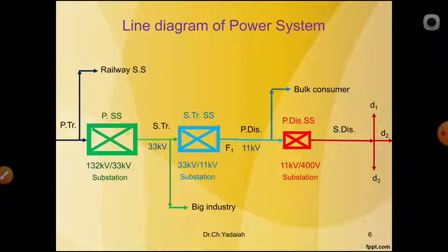Distributors are the conductors from which a number of tappings are taken for different consumers. Here the current is not constant, and it is mainly designed based on voltage drop. These are the things you should know about feeders and distributors.